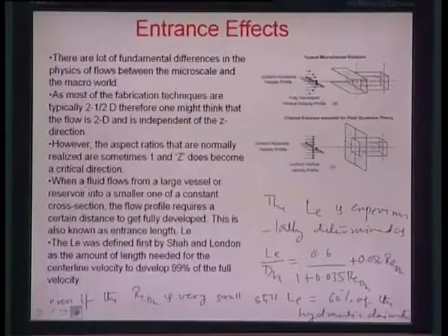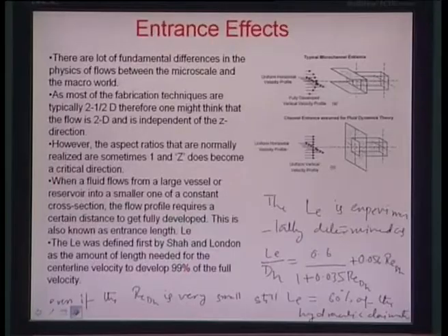Now in cases of microchannels, this length, which is also known as the entrance length, where the flow profile takes to get developed fully, is also a function of the Reynolds number, and it is very critical to design microchannels by assuming what the entrance length would be, over and above which the flow is fully developed within the microchannel.